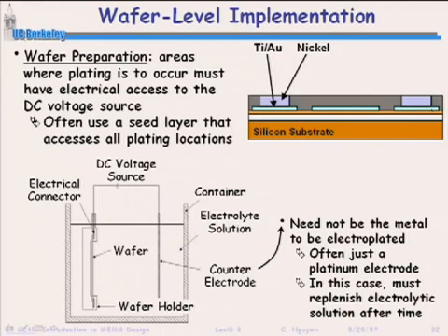But in this case, you put a seed layer down, this time all nickel. Maybe put a photoresist around this to mold the electroplating. And when you've molded this, you get electroplating only between those molds. That creates the structure. You can then remove that photoresist mold.